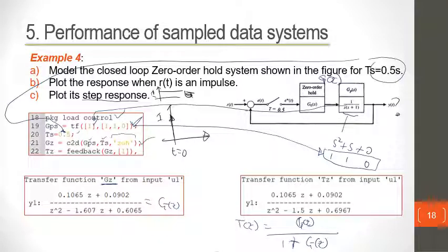code is by simply writing this code here. So this code shows that there's a feedback loop, a unity feedback loop connecting to that, and then this should give you this transfer function T(z). Basically, you can also calculate it yourself manually, but you can do it in software. This will give you that as well, so you can use this to verify your calculation. In this case, we have just managed to model this zero order hold system closed loop transfer function, which answers the first question here.